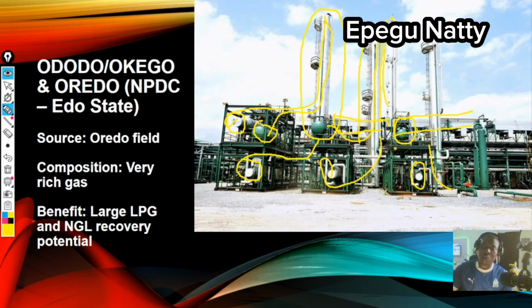I think the stabilizer column should be somewhere around here, somewhere around the background there. And then one important equipment we have here is the TEG contactor. This TEG contactor is what removes water from your system. Okay, so we have regeneration that takes place and all the rest. A lot of this we're going to be talking about in this our DCS. I think I've talked about this, but operationally we're still going to talk about it.